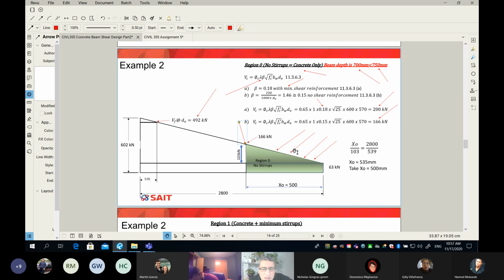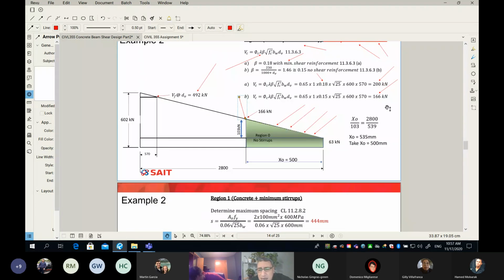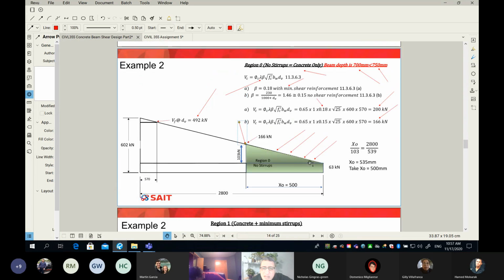Are you guys following? Yeah, that makes more sense now. Okay, so guys, here is the point, which is kind of one penny math. I need to find where I should end my region number 0, where I have no need for stirrup. Very simple.